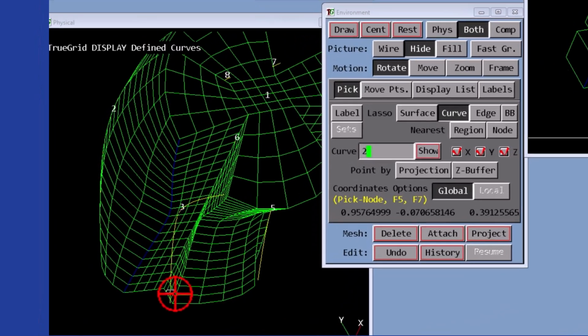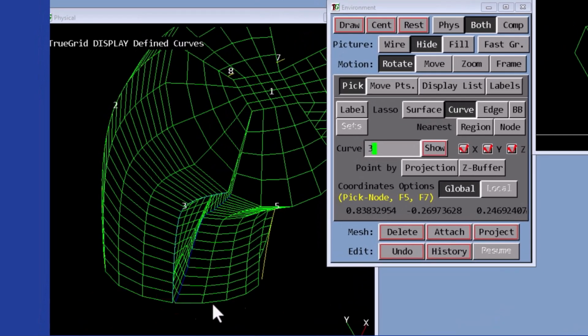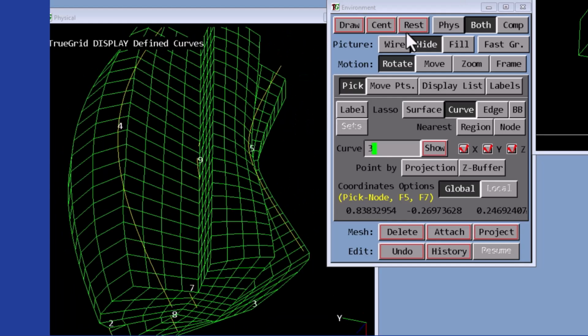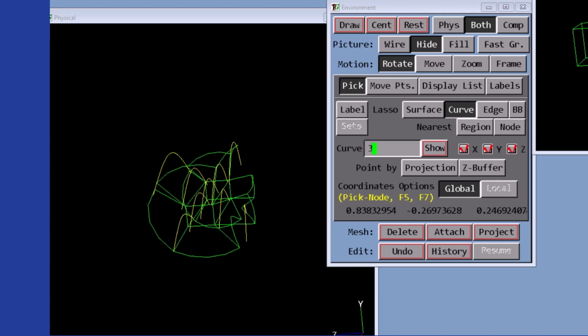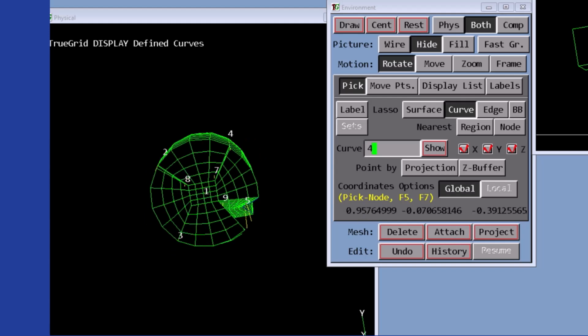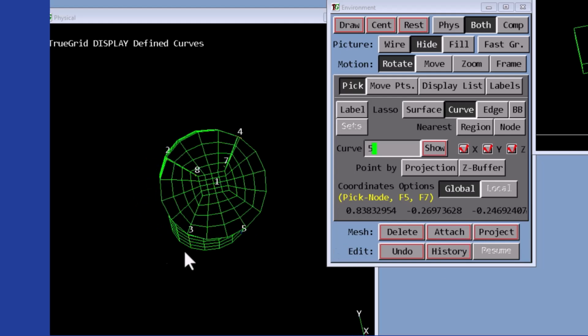Similar steps are taken to attach the opposite edge to the same 3D curve. Select the edge in the computational window, select the 3D curve, and attach. Each pair of edges must be attached to the appropriate exterior 3D curve for each corner block that was deleted.